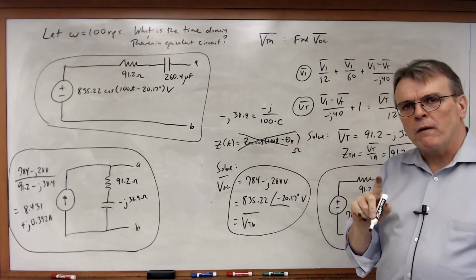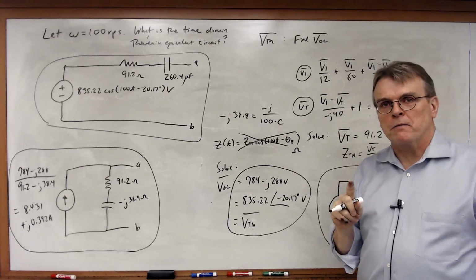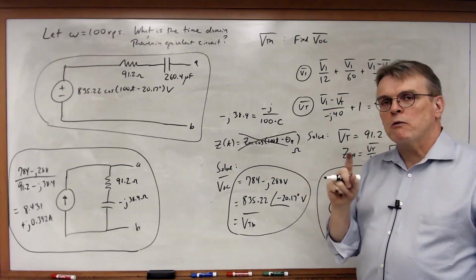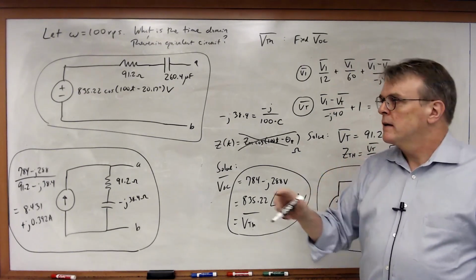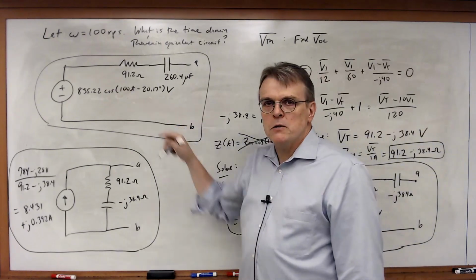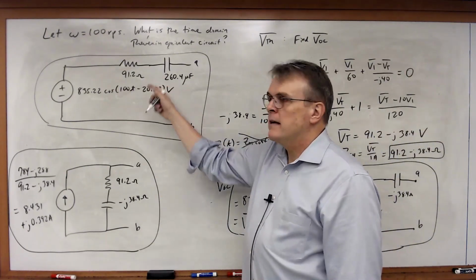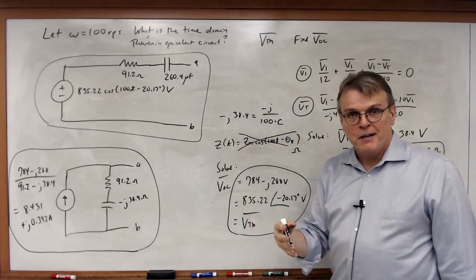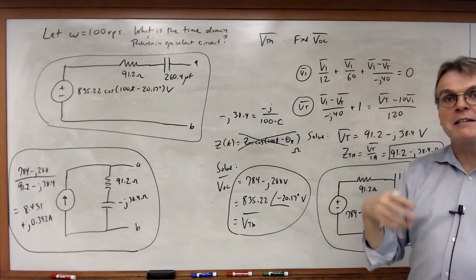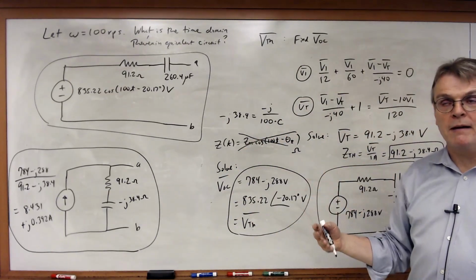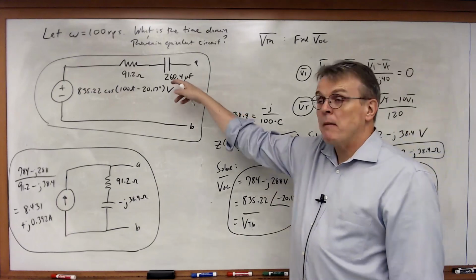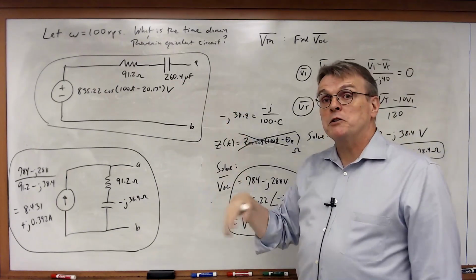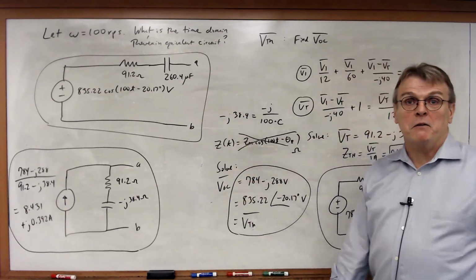As we said before, an impedance is not a phasor. A phasor means you're representing a voltage or a current in terms of a sinusoid. But an impedance is actually real components with values of ohms in the time domain as well as the frequency domain. And then when you convert inductors and capacitors, then you're going to convert to farads or henries for the units.